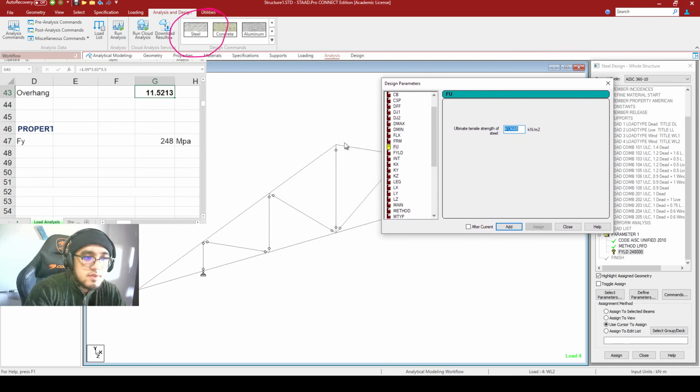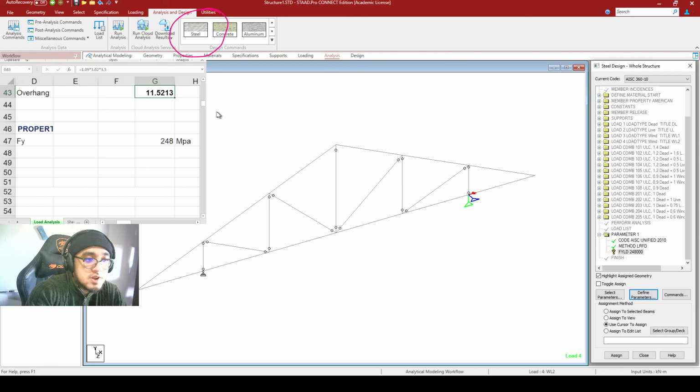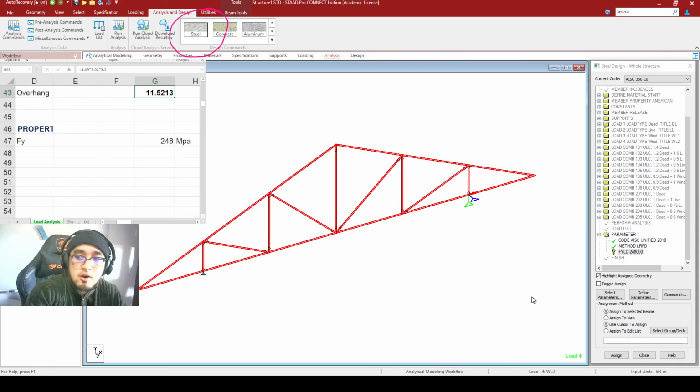But since I want our steel section right here to be welded, its connection to be a welded connection, we wouldn't be needing the ultimate stress kasi wala naman tayong tensile rupture stress if we would be making use of welds. Magkakaroon lang tayo ng TRS if gumamit tayo ng bolts. So if you do not believe me and student ko kayo ng steel design, bawiin ko yung grade nyo. Pero biro lang yun.